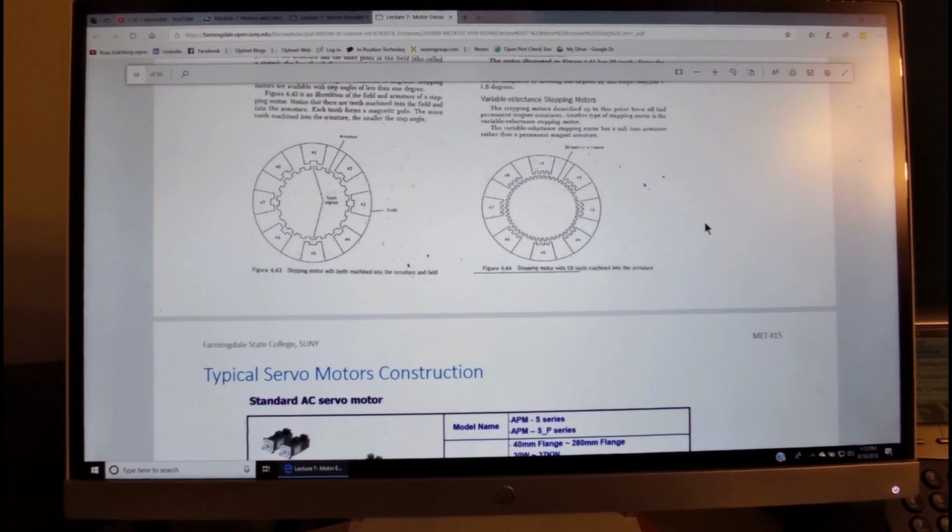Here we see an example of a stepper motor, as we saw earlier. This is a switch reluctance so-called stepper motor. When we excite the poles over here, the teeth of the stepper motor will line up such that the magnetic flux will have minimum energy. That is when this slot exactly lines up with this notch.